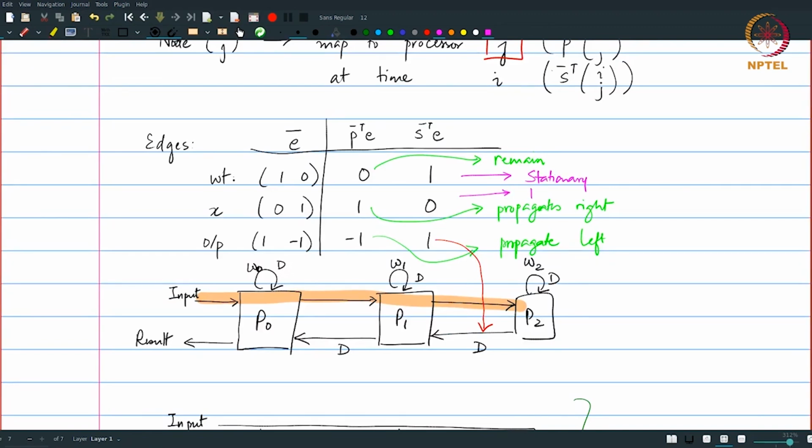The inputs are broadcast to the right, and the results or outputs move to the left, one clock cycle at a time. You can once again see why something like this would be called a systolic array architecture. On every clock cycle, you can see how the outputs move from one processing element to the next until after 3 clock cycles, they have come out on the left hand side.